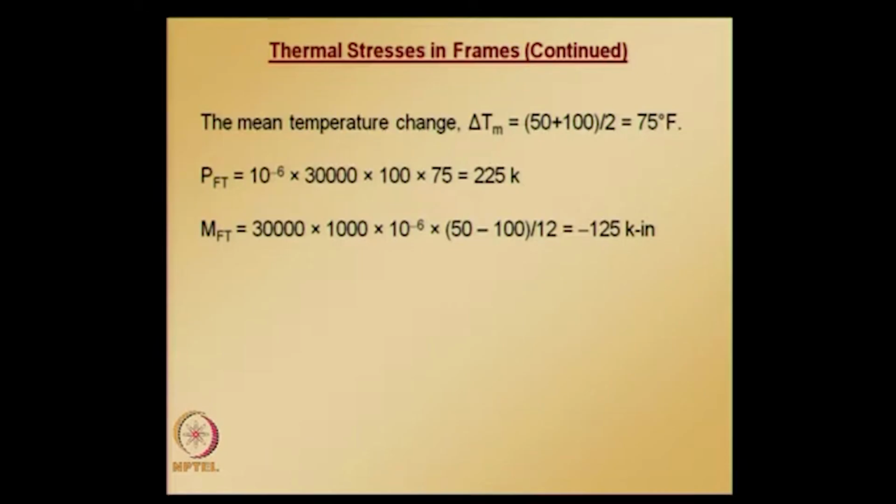and also here the calculation for fixed end moment is also given, and if you carefully observe, even in the fixed end moment equation there is no length quantity when you are calculating. Basically, fixed end axial forces and fixed end moment are independent of length of element. So these values remain same for both element 1 and element 2. So using these values we can get the equivalent load vector. Direction of these fixed end forces are already shown in the figure.